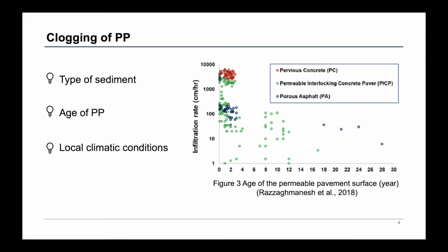The lifespan of permeable pavements in arid areas is longer than that in the wet areas. In addition, larger rainfall intensity may lead to an increase in fallen leaves on the ground, which is worsened by stormwater that can break them down into finer particles. So, we need to better understand the clogging mechanisms and maintenance methods in tropical areas.